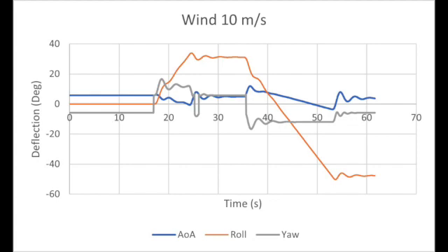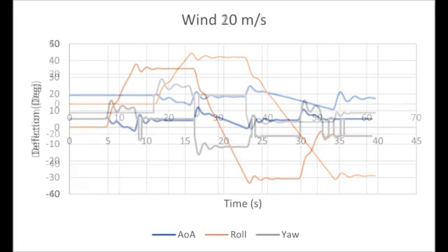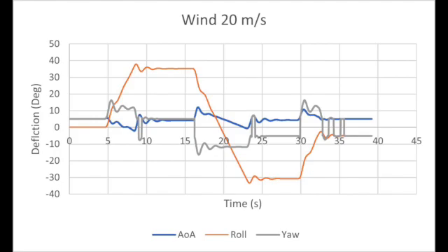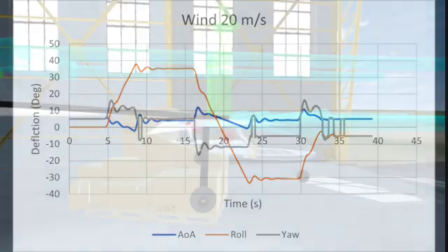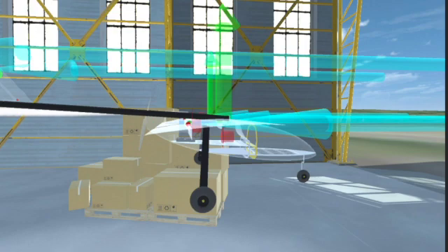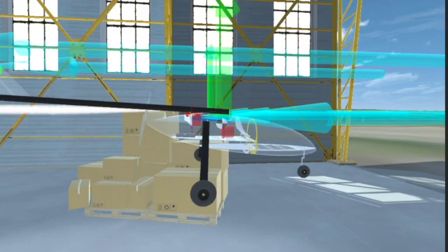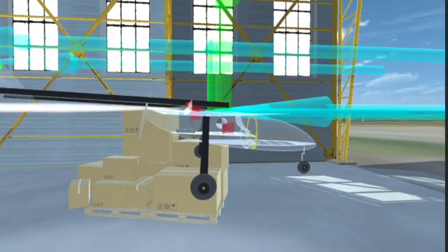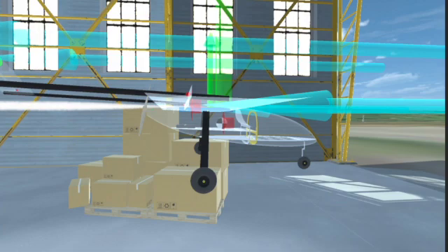The comparisons of these two wind speeds show that at faster speeds, it takes less time to subside, which results in a less intense oscillation from the system. By varying the center of gravity vertically, the response in pitch also varies respectively. A position which is too high would lead to a large nose-up pitching moment being induced, whereas a position too low would create a large nose-down pitching moment which could lead to premature stall.